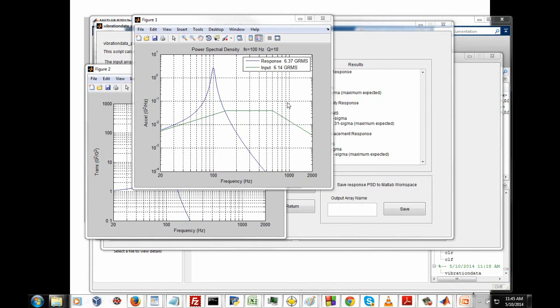Well, if we can use a laser vibrometer, we can get a better measurement because there is no mass loading effect. But we need line of sight to do that, and also more money in terms of instrumentation. But the fact is, in many cases, we don't even have the chance to do this type of test.